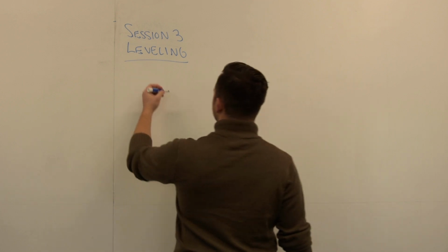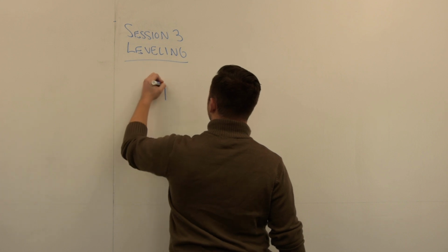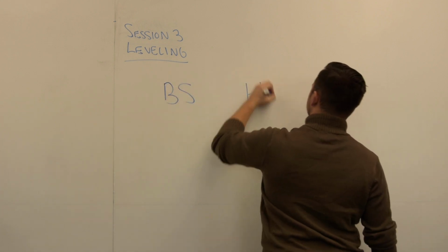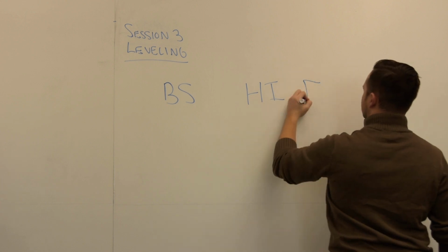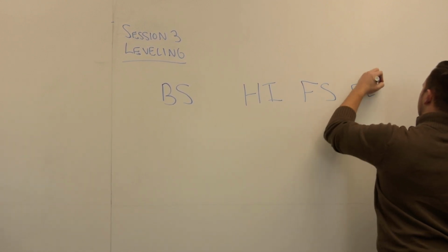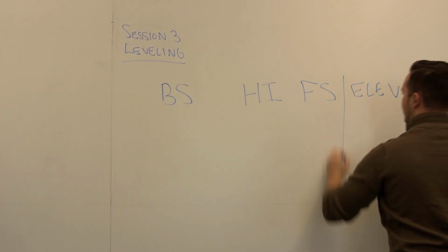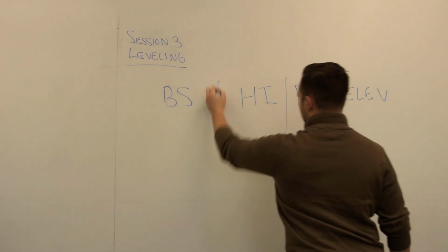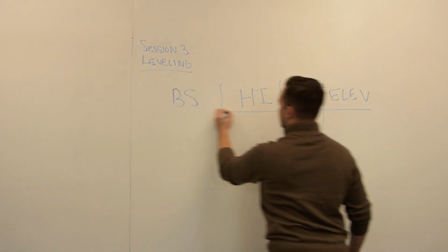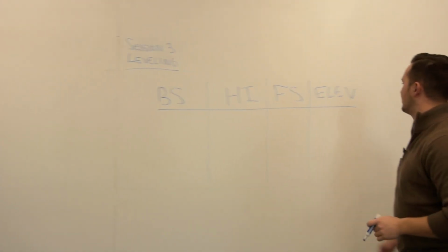We'll be looking at these main components: a back sight, height of the instrument, foresight, and an elevation. These are your 4 main components that will be shown on your field books. And I'll get out of the way to make sure that everybody understands that.